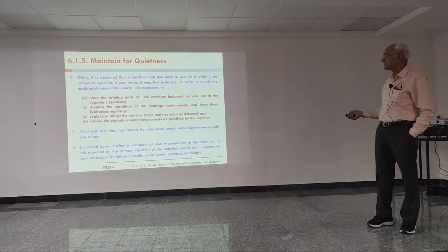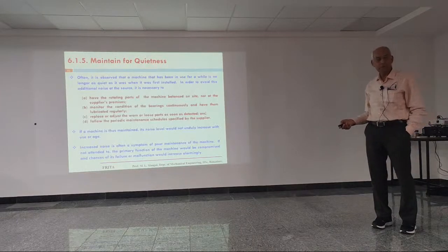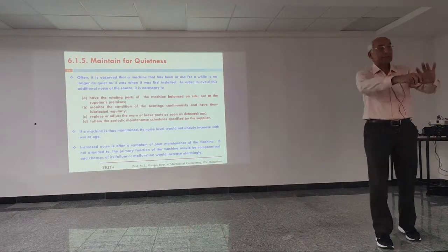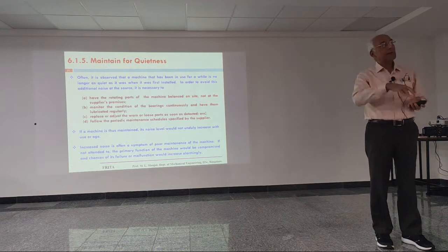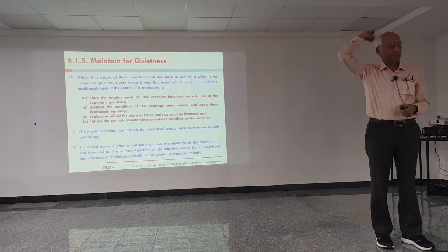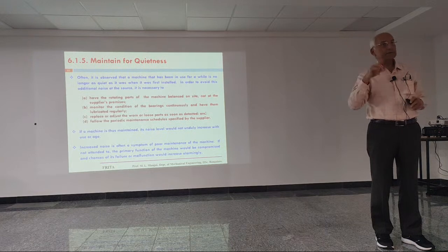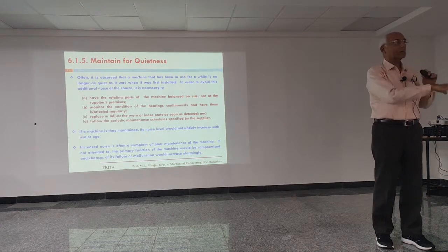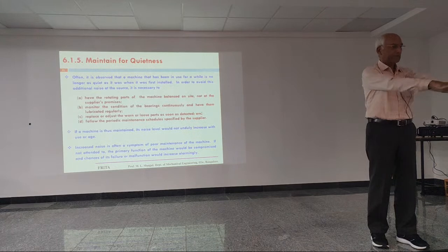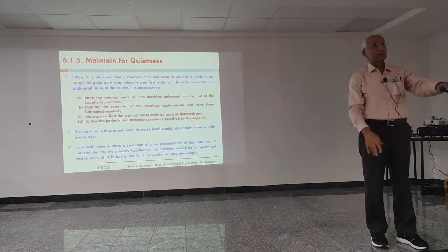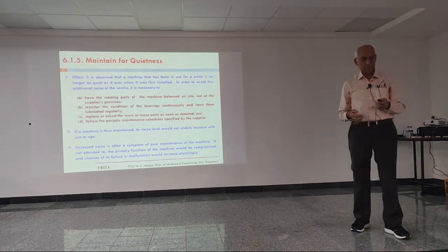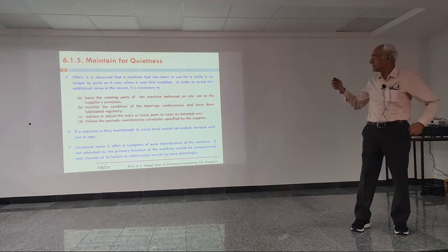In order to avoid this additional noise at the source, it's necessary to have the rotating parts of the machine balanced on site, not at the supplier. It's a very important thing. Often, when they sell you something, they say it has been balanced. No, when it is balanced at the supplier, it is not sufficient. During transport everything changes. Finally, when they install it in your workshop, it will have so much unbalance and produce a lot of noise, and also wear and tear.